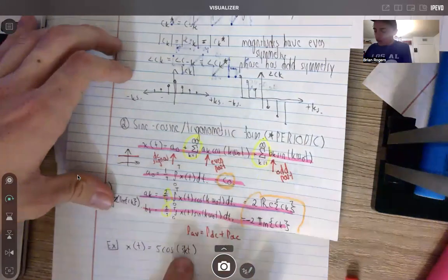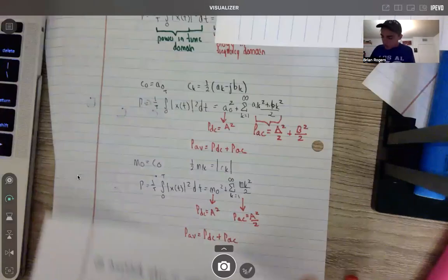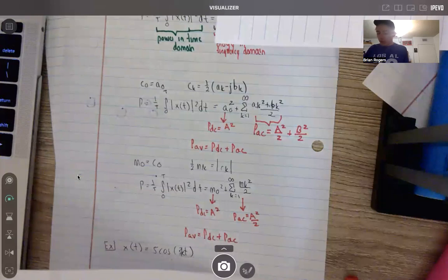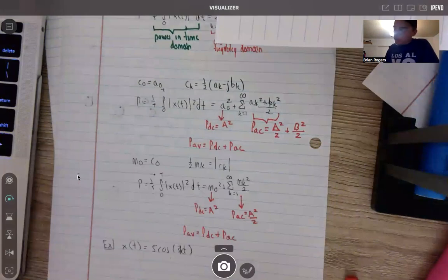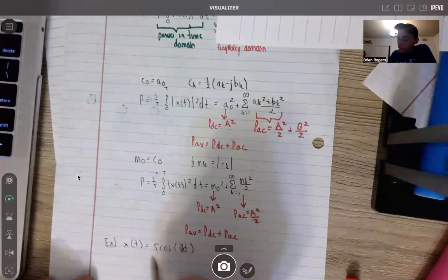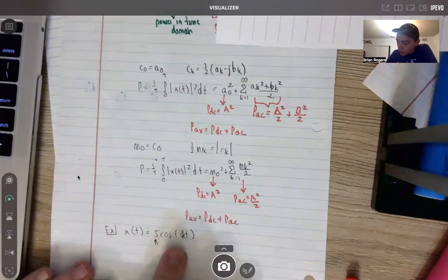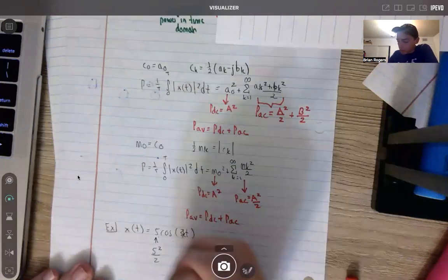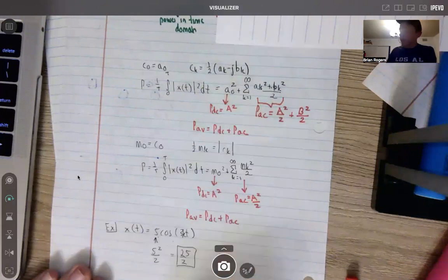So this could qualify as trigonometric, but also the other way here, it doesn't have an offset, but it looks just like this format too. So it looks like both the amplitude-phase form, because the offset would be 0. But remember, it's the same exact thing. You just take the amplitude and you square it. This is an AC form, so you take the amplitude, square it and divide by 2. And so you get 25 over 2. That is finding the average power.